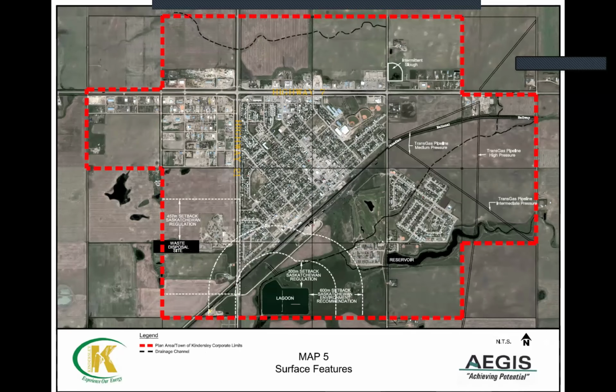The setback is a portion, a strip of land around certain items like the lagoon that cannot be touched and needs to be preserved untouched. So a highway, a road cannot pass through those. You can also see the waste disposal site on the left, middle left, and you also have a setback for that one, according to Saskatchewan regulations, 457 meters. So all that is in the white dash area is area that are setbacks, environmental setbacks that you cannot pass by with any future road or highways.